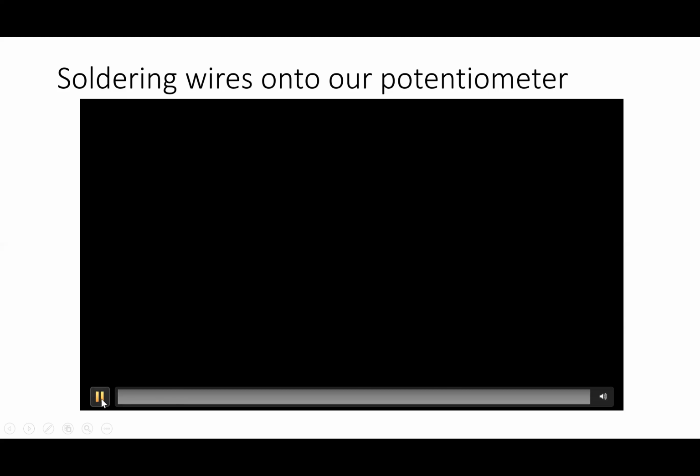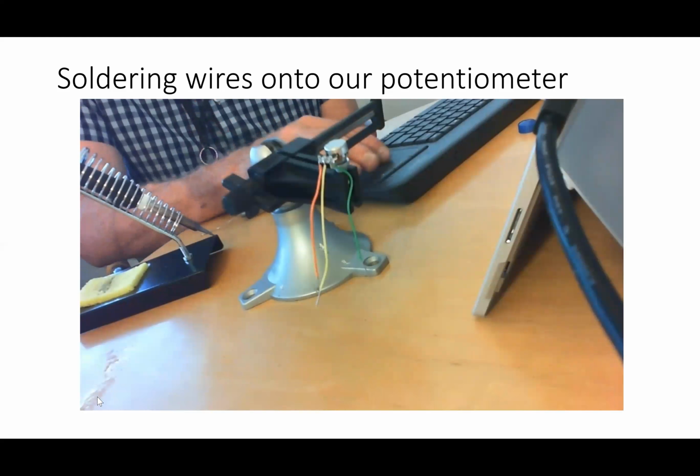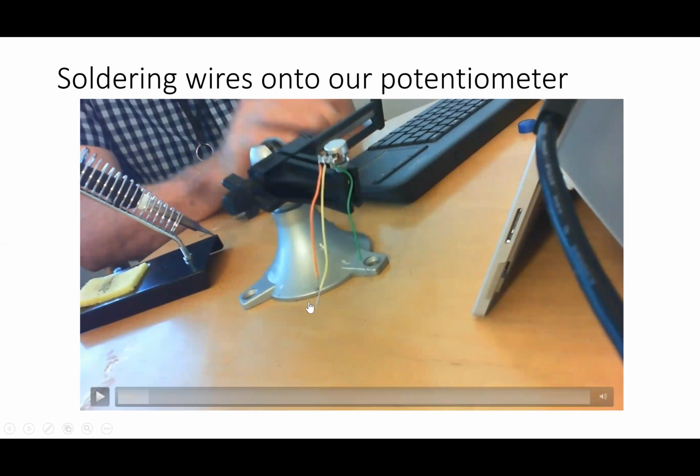Now, the first thing I want you to notice here is that I have cut these wires here to have quite a bit of free wire at these far ends. Recall this is because these wires like to break here where the insulation joins the bare wire, and you don't want them breaking off in your Arduino or breadboard without the ability to pull them out again. I've also hooked the wires through the tabs here. They're swinging loose, but they're mechanically connected, and I put this in a little vise so that I could hold it there while I solder.